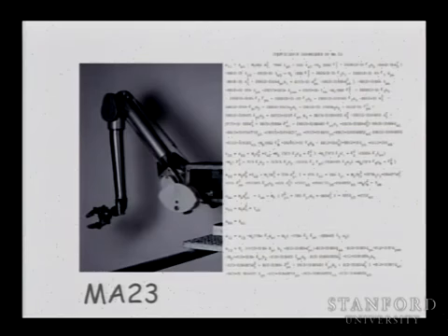viewed from the first joint when you move. So this inertia is changing as you move. So imagine if I'm considering the inertia about this axis, right? If I'm deploying the whole arm, the inertia will increase. If I'm putting the arm like this, I will have smaller inertia about this axis.